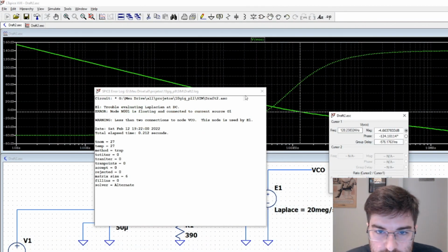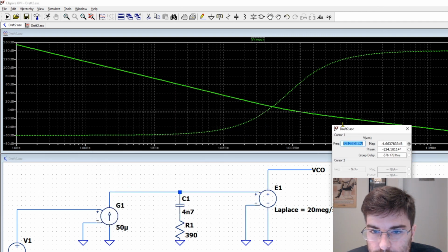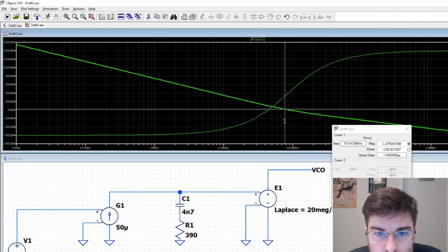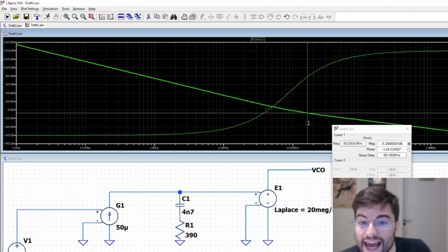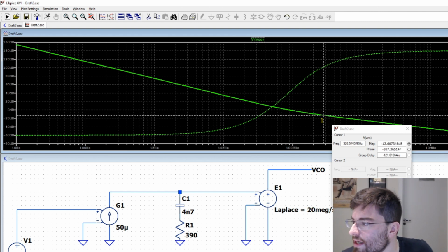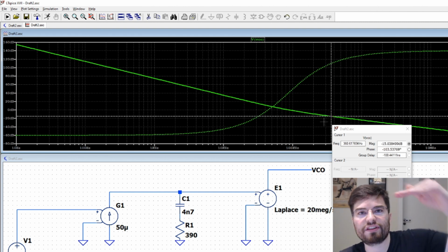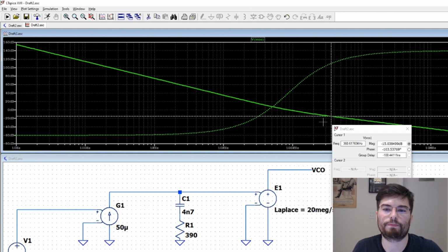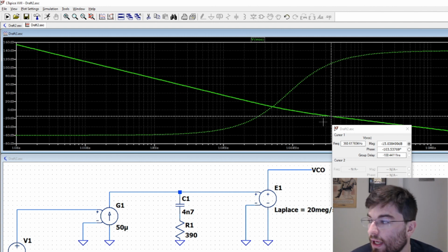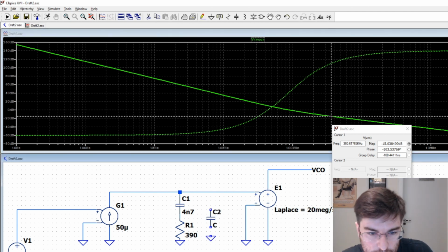After we cross 0 dB, we can add a pole again here, somewhere here, to stiffen the curve again, closing the loop more. Making the loop filter with a higher slope, a 40 dB slope. Now we have a 20 dB slope on the closed loop response, and we can have a 40 dB slope in the closed loop response by adding a capacitor here.